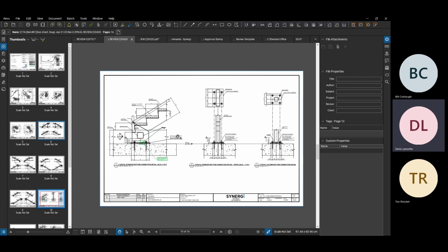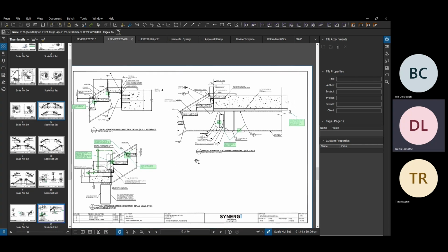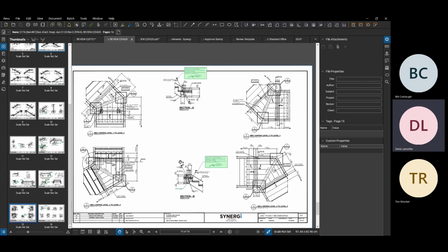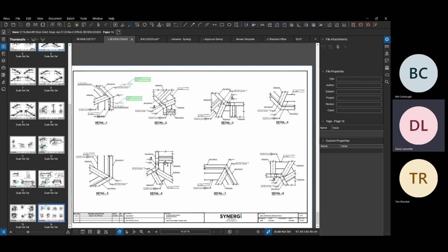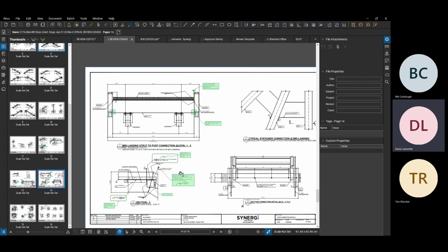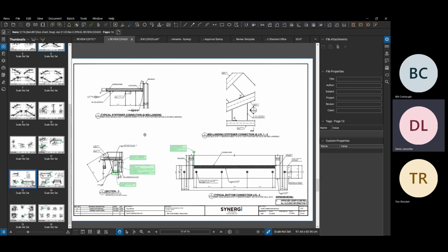We talked a little bit yesterday about splice joints in stringers. So anytime there's a splice joint, if there's a CJP weld, we're adding a new detail clarifying how it's done. I don't think I have it in this set. This set here was done before we had that issue. But just fall back to what we talked about yesterday for the splice joints. And just make sure they're detailed correctly. If it's a mechanical joint, make sure that that's detailed correctly.